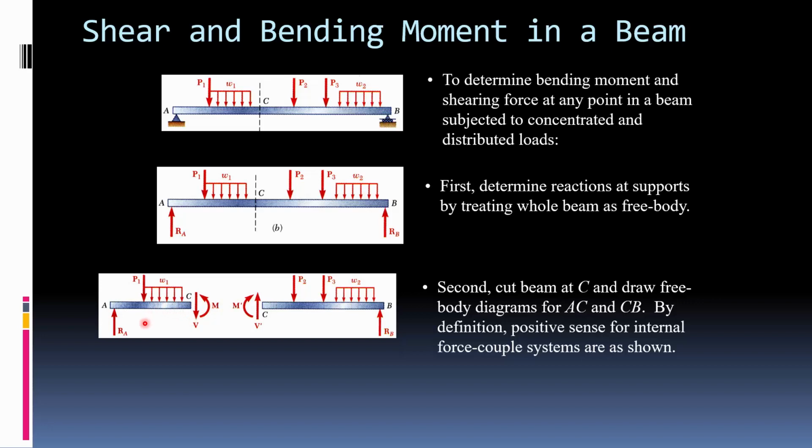How do you know that? Well, quite frankly, because when you do the math, all of these forces end up being equal to these 2 forces combined, all the ups equal the downs. And it's extremely unlikely that at this point this force is going to be equal to that. So what ends up happening is this shear force is compensating for the difference, because again, everything needs to be in equilibrium. This part is in equilibrium. Now, obviously, if you cut it and just left it there, it wouldn't stay in equilibrium, but if you were to somehow look at the forces inside, it's going to be in equilibrium.